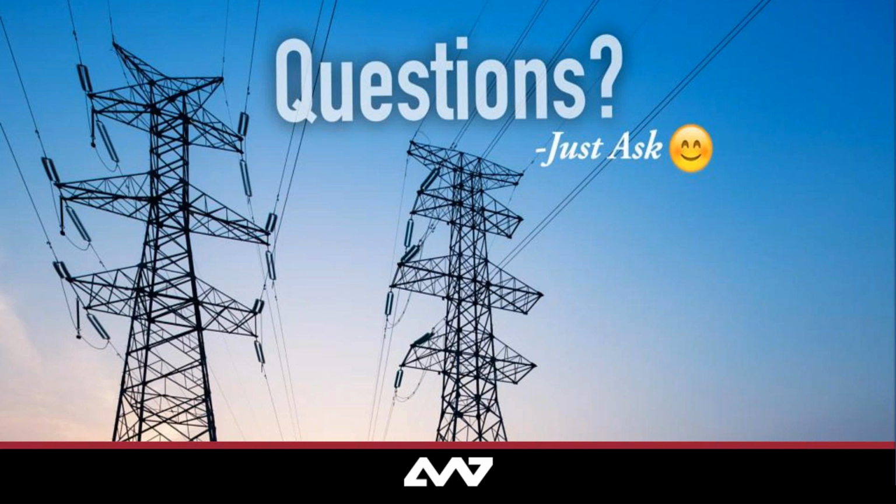So the DNP spec says the default is 20,000. Every outstation has to be able to listen on port 20,000. Every master has to be able to connect to port 20,000. However, if your device is capable of it, you can choose to listen on different ports. You can choose to connect to that same matching port from the master. So it is not required to always listen on 20,000, but it is required to have that capability.